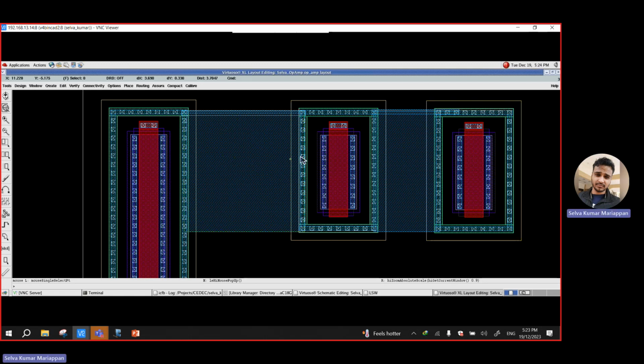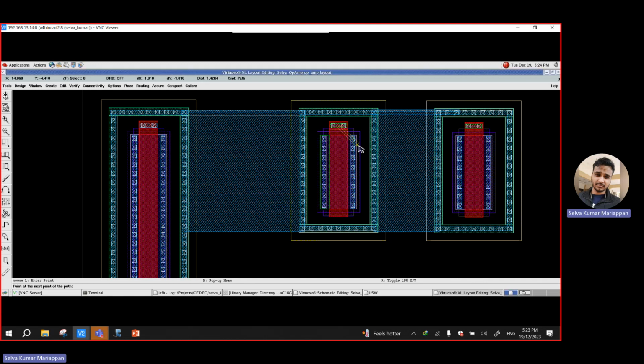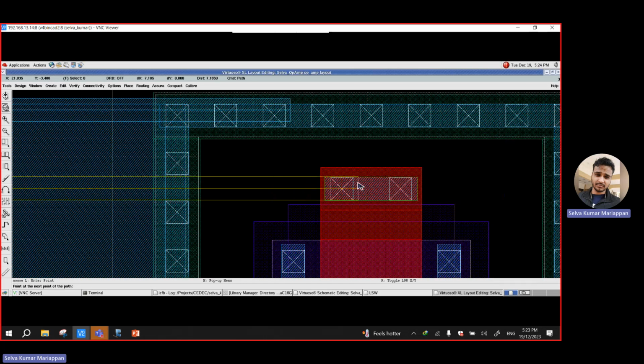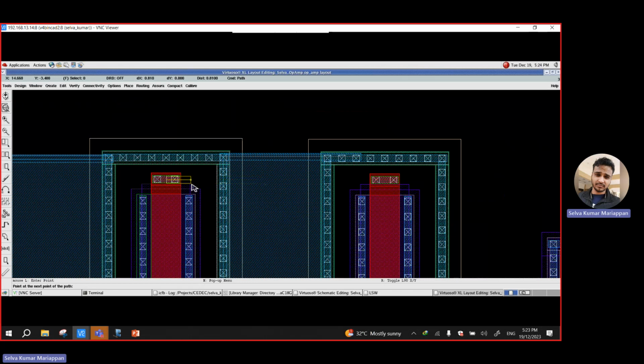Now I want to pull from here, metal 1. Okay, I want to pull it here. Can you see or not? It highlights for you. Okay, see, it's in green color. But can I do that with metal 1? See, it blinks. Why? Because it's shorted here.